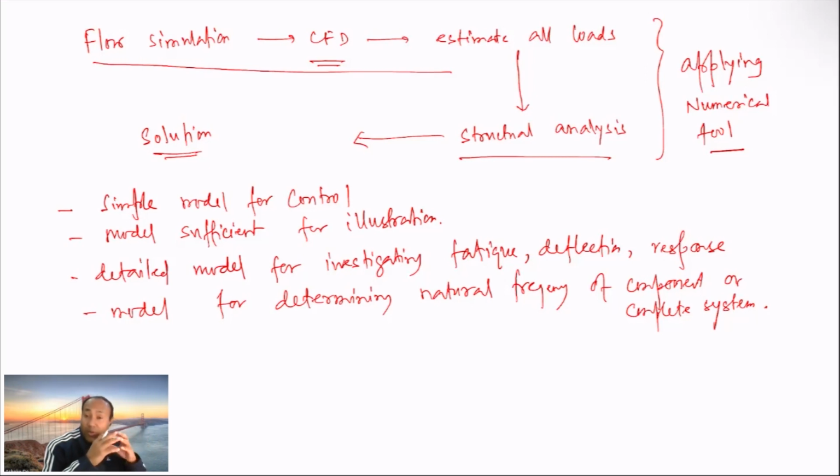One can do it in slightly segregated ways, like doing the aerodynamic load calculation through CFD and then using those loads for the structural responses, or have a coupled system, a complete aeroelastic behavior, which is really complicated, even with the computational resources that we have today.